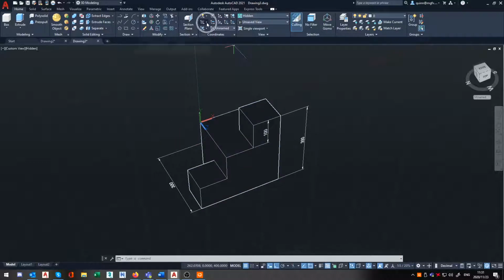We would then need to use something like our rotation, which I used previously, but I didn't mention what I was doing. So in other words, I can use maybe rotate around Z and then manipulate my X, Y into position, or rotate around my Y and get my X, Z into location. This does, by the way, help if you've got your ortho mode on. You can then also do, of course, the X, which I'm not going to really mention here because it's the same type of thing. So rotate around the X, rotate around the Y, or rotate around the Z axes.